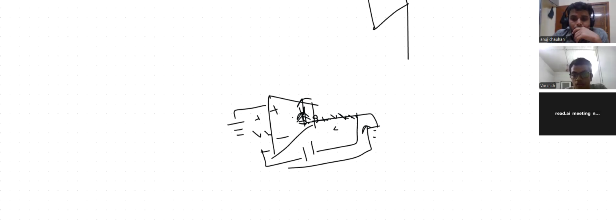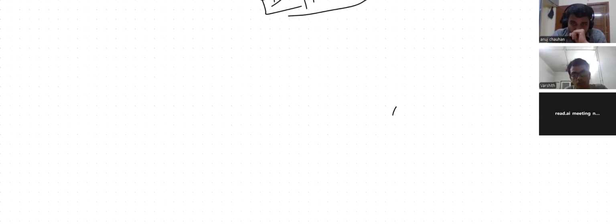Vx into sCc equals gm times Vx. So here you are also getting a right side zero. What is the problem with the right side zero? It adds phase, sir. A pole adds minus 45 degrees, but the right side zero is the same, sir. The right side zero will add a phase down, negative phase, sir.